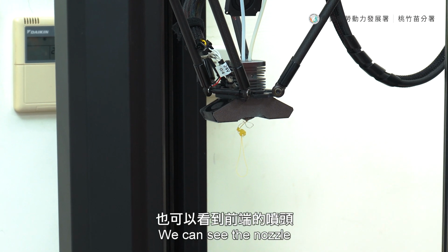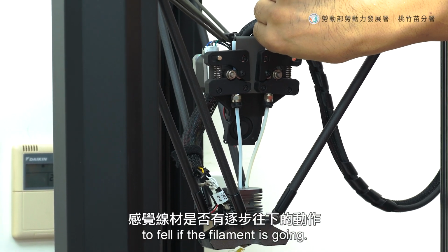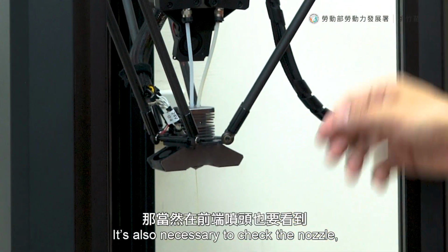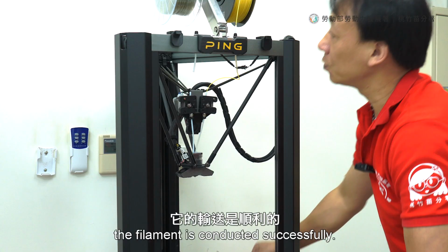We can see the nozzle squeeze out extra material. We can use our right hand to feel if the filament is going. It's also necessary to check the nozzle, to see if it's feeding smoothly. This way, the filament is conducted successfully.